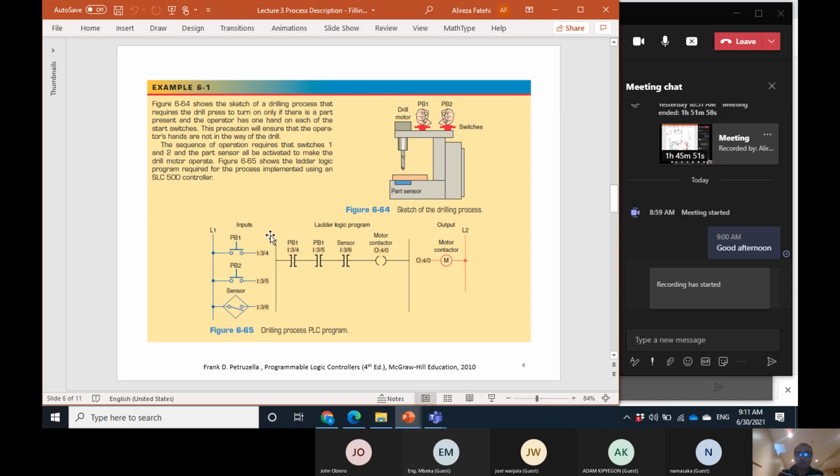To build the program, we should also check the type of the switches, and the connection of the switches to the PLC. Establish that connection if it is not established, but if it is, and if documents are available regarding that connection, check that.